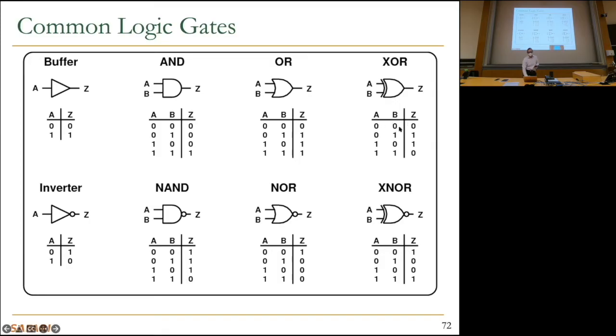So you can see over here, we have a 2-input XOR gate. Wait a second. Output is, okay, let me put it that way. Again, output is 1 if an odd number of inputs are 1. Output is 0 if an even number of inputs are 1. Okay, so I got it better right now. So if you look at here, A and B, only in these 2 cases, an odd number of inputs is 1, so the output is 1. When A and B are both zeros or both ones, the output is 0, essentially. That's the idea. You can generalize the XOR gate, yes.